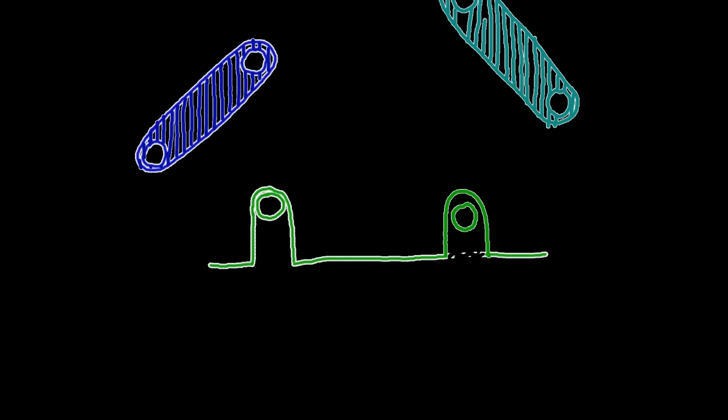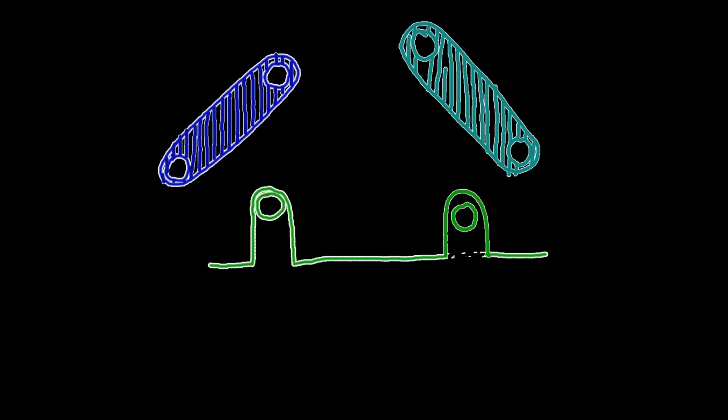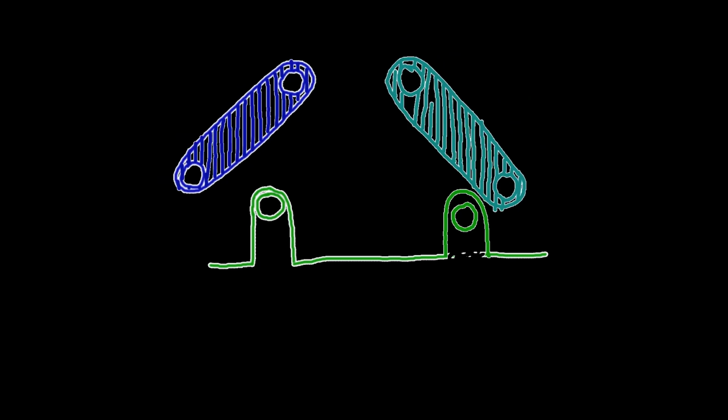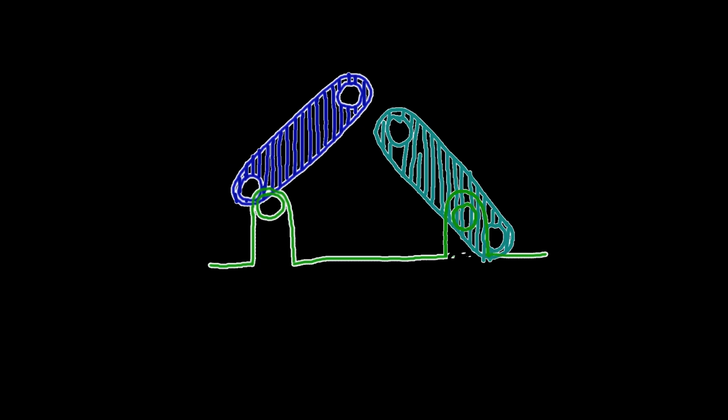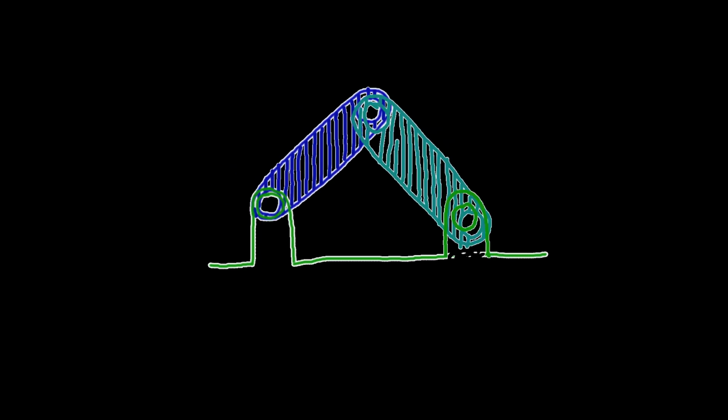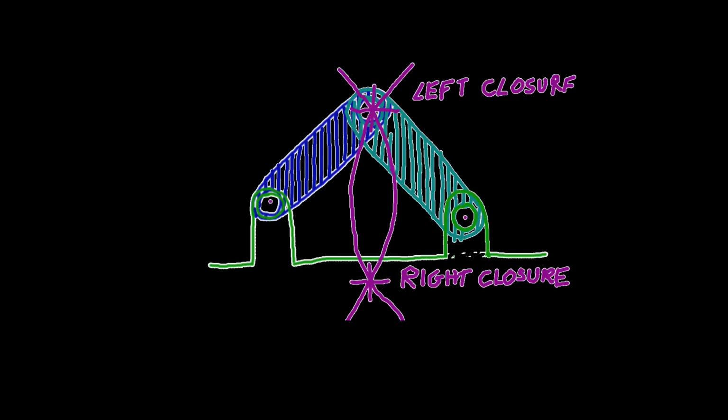3D CAD typically uses iterative solving for mechanisms. They will try and minimize some function of the distances and constraints between mates, for example. MechDesigner solves mechanisms in a completely different way. It solves the geometric equations which describe mechanism groups called dyads. Dyads have 0 degrees of freedom and can be composed to make larger mechanisms without limit.